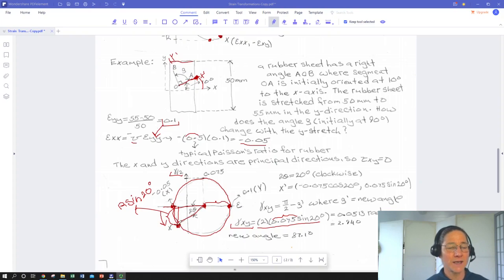We got our point. Then the next important concept we had to relate was shear, shear strain at x prime being corresponding to the closure of this angle. So basically we used the definition of shear strain and said, okay, shear applied at this x prime direction is literally equal to this angle closure.